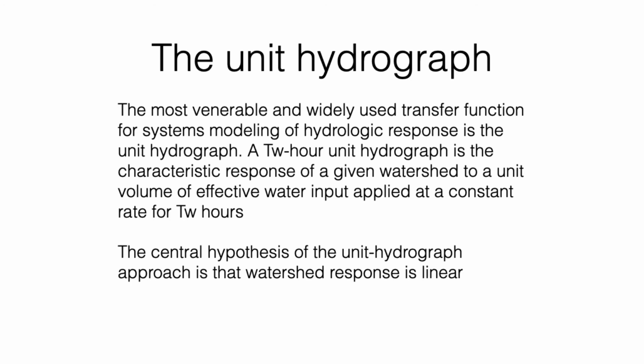Therefore, a unit hydrograph is always linked to a given duration of the storm. A unit hydrograph represents the response of a given watershed to a unitary rainfall event of a given duration. Why is this important? Because we can always decompose any storm into n substorms of a duration equal to the duration for which the unit hydrograph was computed, and then we can compute the total hydrograph by assuming unit hydrographs, each of them multiplied by the total precipitation, or the corresponding intensity, for every substorm.